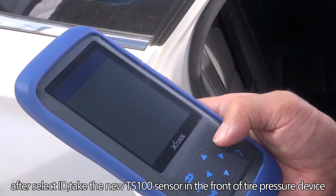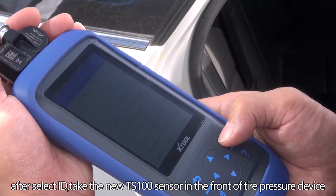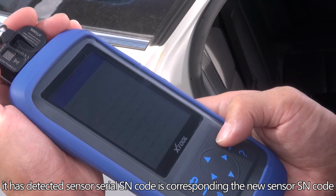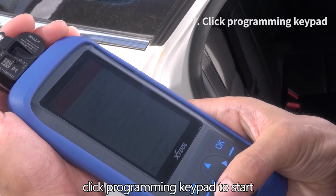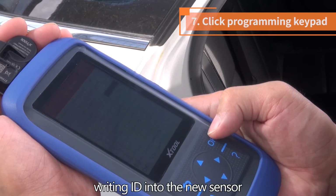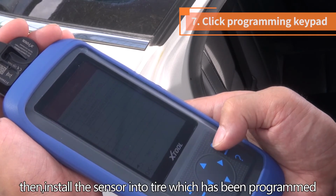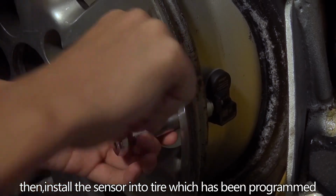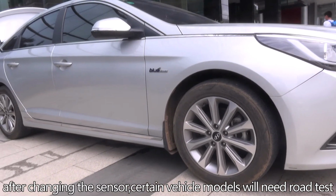After selecting the ID, take the new TS100 sensor in front of the tire pressure device and enter the programming interface. It has detected that the sensor serial SN code corresponds to the new sensor SN code. Click the Programming keypad to start writing the ID into the new sensor. Then, install the sensor into the tire which has been programmed. After changing the sensor, certain vehicle models will need a road test.